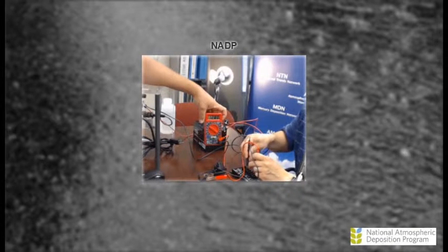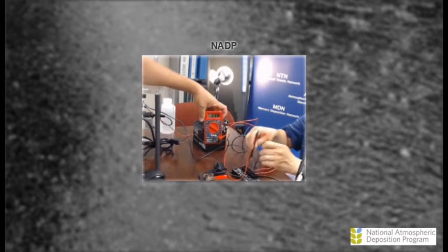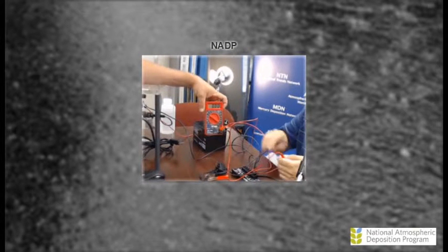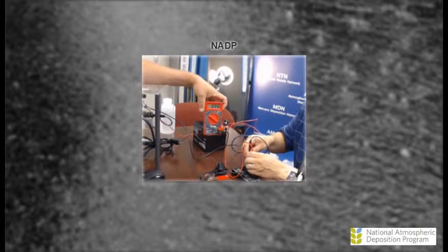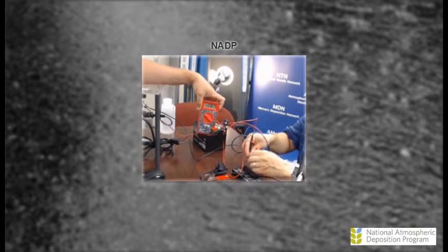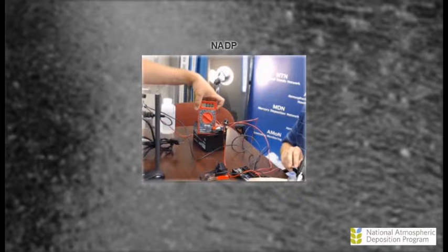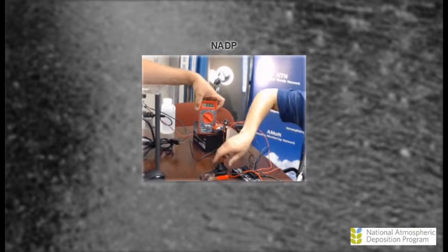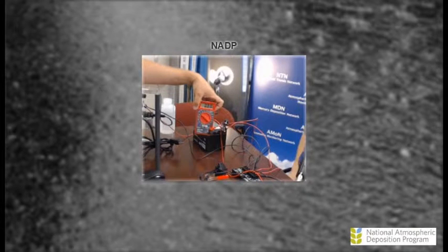As Chris mentioned, though, with the blocking diode, the one thing you do not want to see when you hook these up is to watch your power go down. That's a possibility that the diode could be leaking the power. Yes. And that's where you run into problems with the solar panel not being able to consistently regulate the amount of voltage to go through all the way to not only the batteries but to the collector as well.